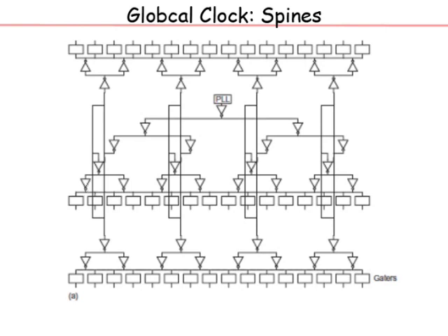The midpoint will be in between the two midpoints. You can imagine that you have two ramps, and then the output will start from the bottom of the first ramp and end at the top of the second ramp. So the midpoint will be between the two midpoints, but the edge rate will also be less. I mean, it will rise slower. So that is the degradation which happens, but the midpoint delay gets averaged out.